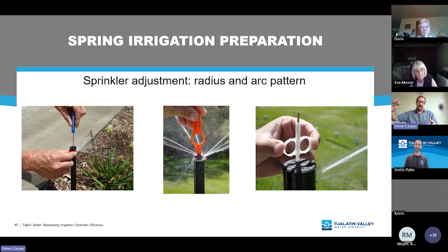Conversely, if you schedule that zone based on how the rotor applies water, then the area watered by the pop-up fixed pattern spray is going to overwater, just by the nature of their precipitation rate. So you really want to avoid that. The exception, and this can be a workaround because unfortunately it's fairly common that people do this and then somebody else moves in and has to resolve that situation, is that these multi-stream rotating high efficiency nozzles can be more effectively grouped with a single stream rotor because they have a more similar precipitation rate.